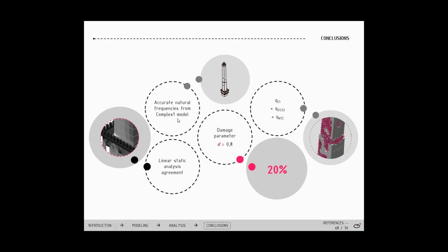From the modal analysis, we can conclude that the more complex the model is, the better the actual response of the tower was achieved. However, the Winkler model adopted for the soil structure interaction turns out to be too flexible for this three-dimensional finite element model, forcing the stiffness values to be higher than expected. So in this way, further research in the soil structure interaction for this type of structures is strongly advised.